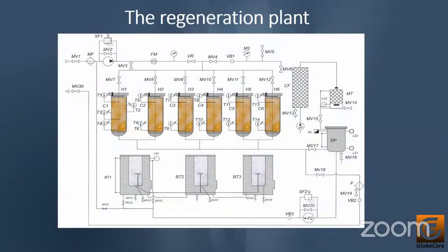This slide shows a general view of the machine. The oil passes through the columns, the function of which is to capture the degradation products. First, the columns are filled with oil, and you also need to have a supply of oil that will allow you to maintain the process properly. As soon as the need arises to activate the Fuller's earth, the oil from the columns must be drained, and the process of burning pollutants inside the columns can be started.